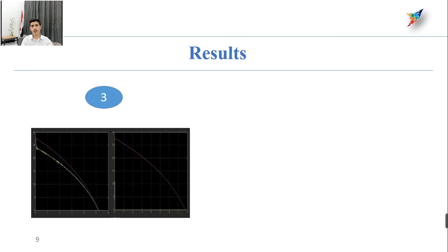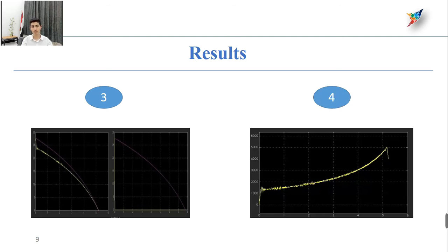The torque of braking is constantly changing when we have anti-lock braking system, as shown in figure 4. While without ABS, it is constant and equal to 4000 Newton meter. This shows how the controller regulates the value of the torque.